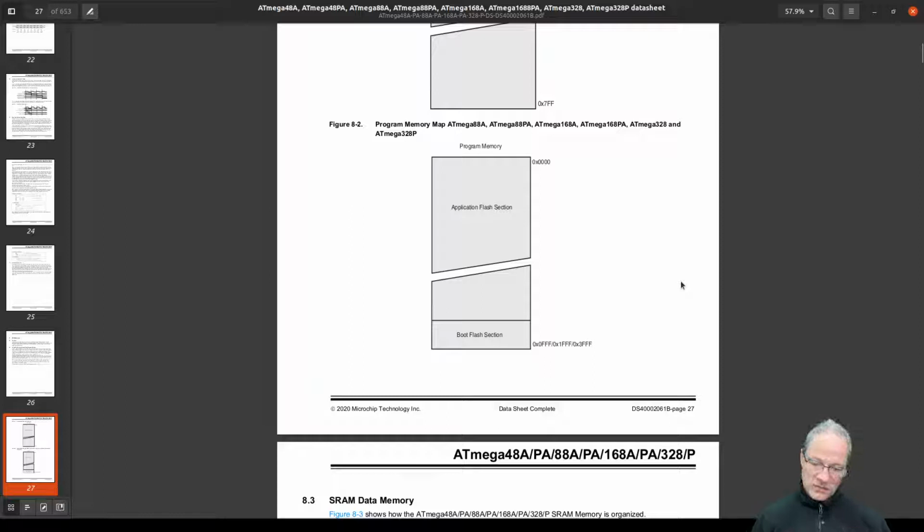And when you start it up, there's this little program that runs first. Or even when you reset, that's what's being started. And then it starts a certain program from some memory in the application flash section. And that's how the program starts. And then we did talk about the Watchdog as well, which is meant for saving us if something goes wrong with our system. Saving through resetting the whole system and hoping that then the system can pick up whatever it left and keep on running.